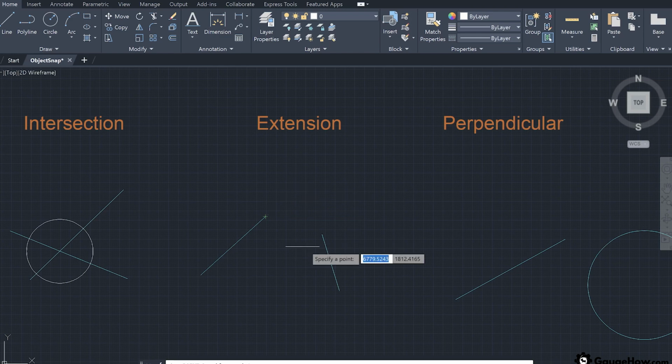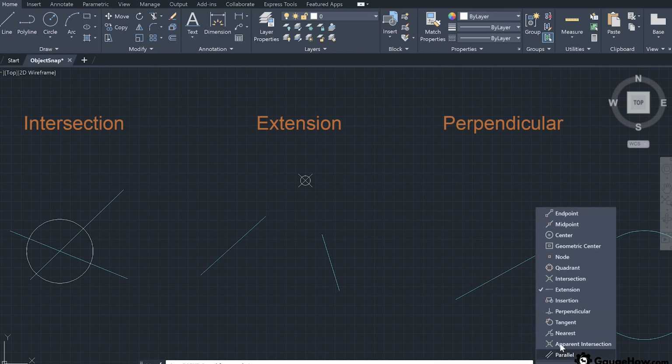Similarly, when I move the cursor to the another line, again from the end point to the upper side, you will see that again a reference line is created, and when these two lines get intersected at that particular point, we will get the cross symbol, and easily the cursor is pulled to that point. Now I will select that point, and we can get the intersection of the two lines due to this extension snap enabled. Next, I will deactivate the extension snap and activate the perpendicular snap.